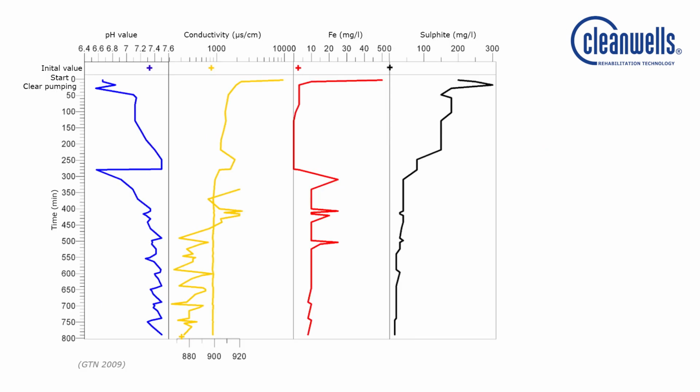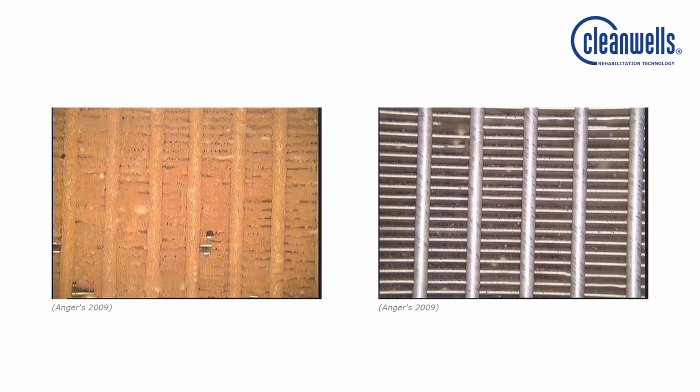Additionally, the control can also take place by regular measurements of the electrical conductivity and pH value, as well as iron and sulfide concentrations, as documented also in KS9. A CCTV camera inspection is another standard control instrument between different phases of the rehabilitation procedure. Here showing KS1, also one of the Berlin wells.